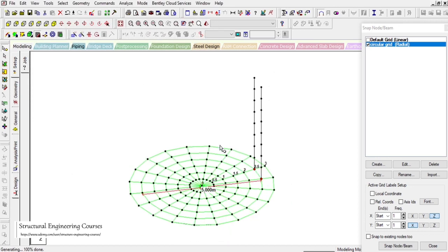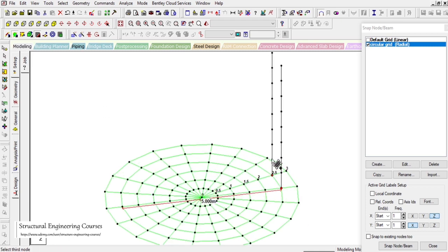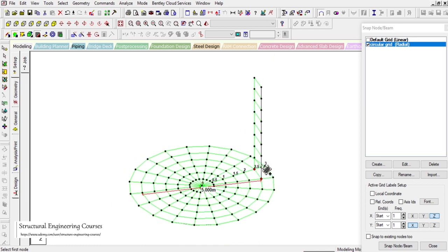So with this option, what we can easily do is just model the plate elements here. Although the link steps option was not a compulsion, it becomes much easier for you to find this perfect alignment for modeling the plates. The link steps option helps us by saving lots and lots of time by automatically modeling the beams along all the nodes. So we select all the beams here,